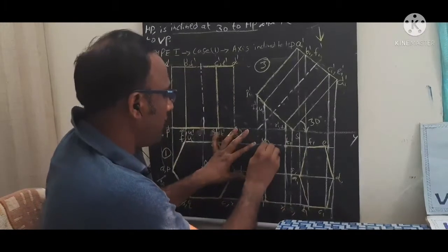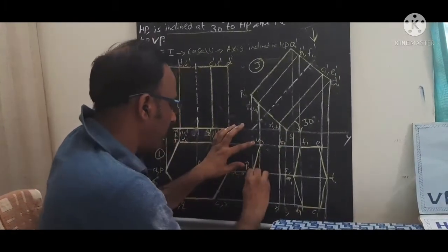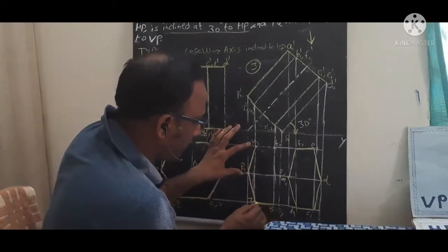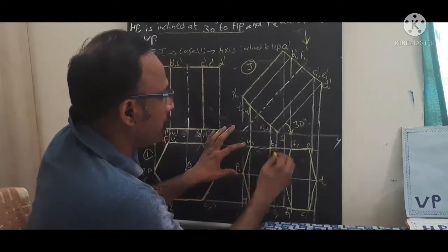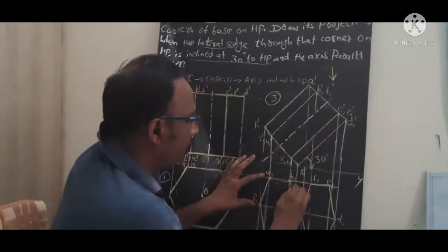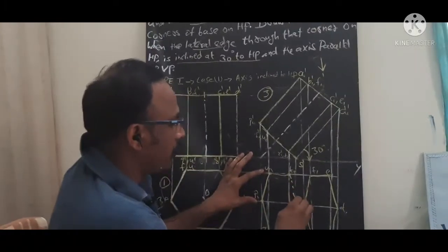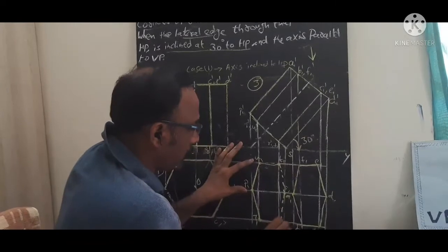Similarly, you come into the back surface, the bottom one. One side is visible. So the visible portion I have drawn as the darker one. This area is invisible. The edge connecting with S dash is invisible. It is to be joined like this dotted line. Similarly, this point we need to draw this dotted line.